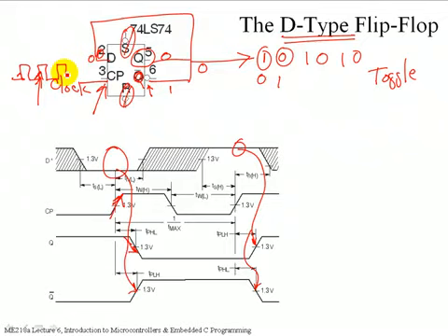Yes? Oh, that's a very good question. What's the difference between the output and the clock? Shift it over a little bit. No, no, no. Be careful. Let's try and draw this out in time. So I get an edge and that causes a rising edge there. And then I go over a little bit, and then I get a falling edge. What happens to my output? It keeps going. So I go over a little bit, it keeps going. Then I get another rising edge. Then it falls down.